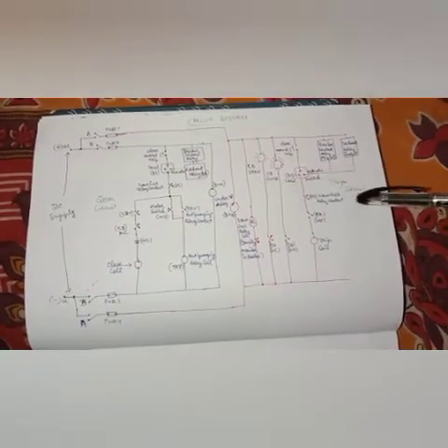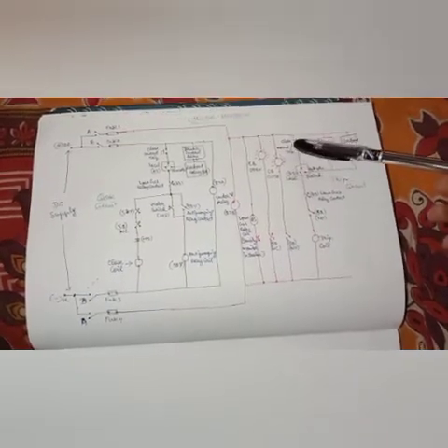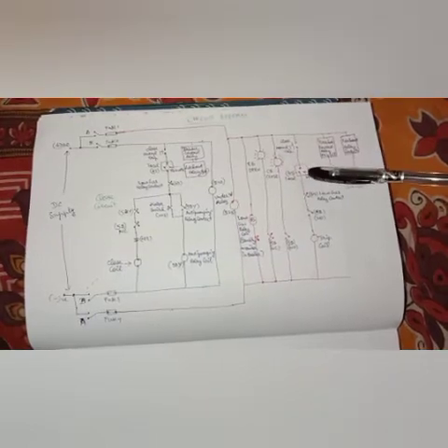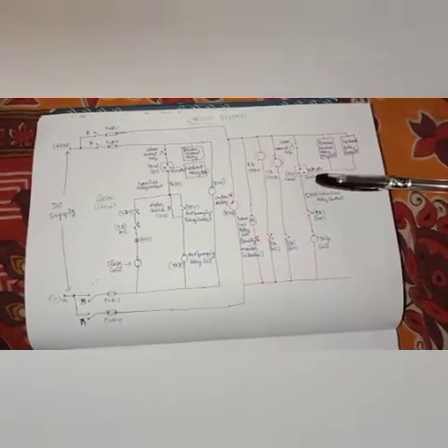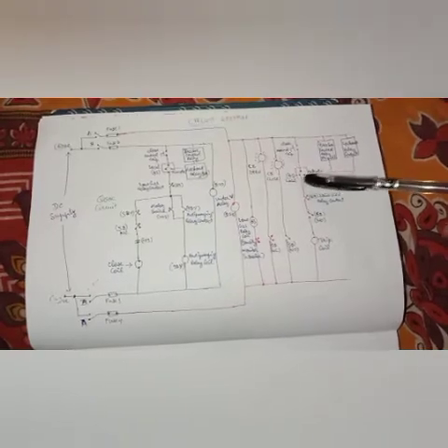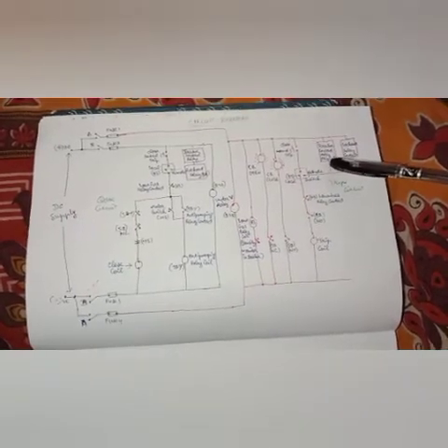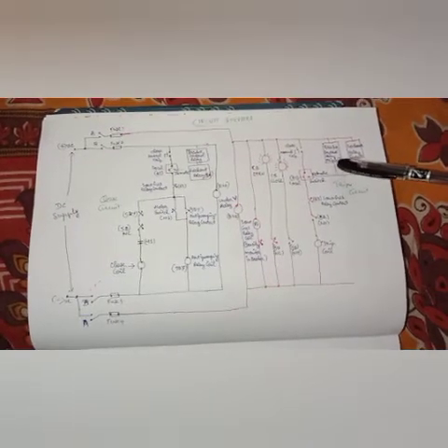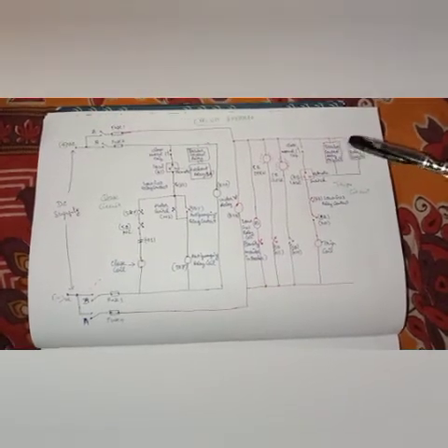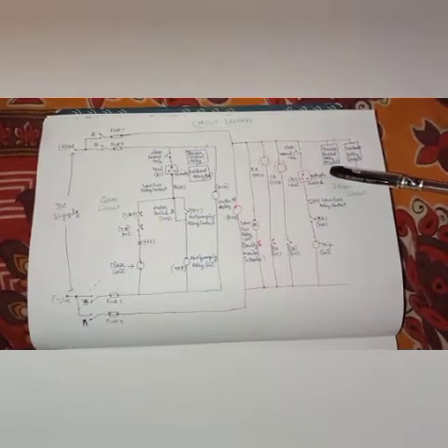Then coming up to the tripping circuits. Here the tripping circuit, same TNC switches and breaker local and remote switches are connected. Here the breaker control relay trip coils, which means the command and the tripping initiation can be given by the breaker control relay tripping coils.